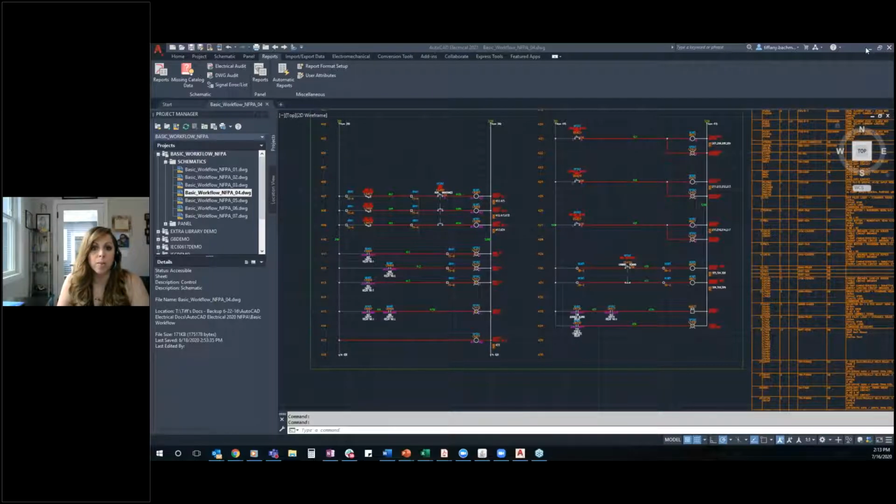Okay, good deal. Yeah, and just for everybody to know that installation and location codes are a great way to filter reports by anything you have. So most customers that I work with typically only use one, they don't use both. And we can talk more if everybody is interested around what truly the installation and location codes were designed for, but I'll tell you what, location code I truly use for the sense of the location. Where is it located? It's junction box 1, it's main cabinet 3, it's whatever, operator station XYZ, whatever you want that to be, I typically use the location code for that.